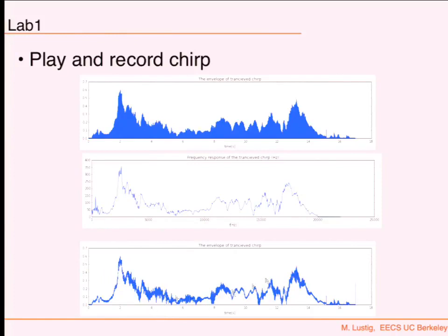So this is the frequency response, and this is from my laptop. It's really loud, and the audio, like the speech. It's not just the speaker, it's also the microphone together, multiplied. So it's kind of hard to differentiate between them. There's actually no way to differentiate. And it also depends on the room. If you change it slow enough, then all these transitions, the reflections that happen, don't contribute much. You get a steady state response. We're assuming that things are not changing over time when we do that, or they're changing much slower than we're sweeping the chirp.